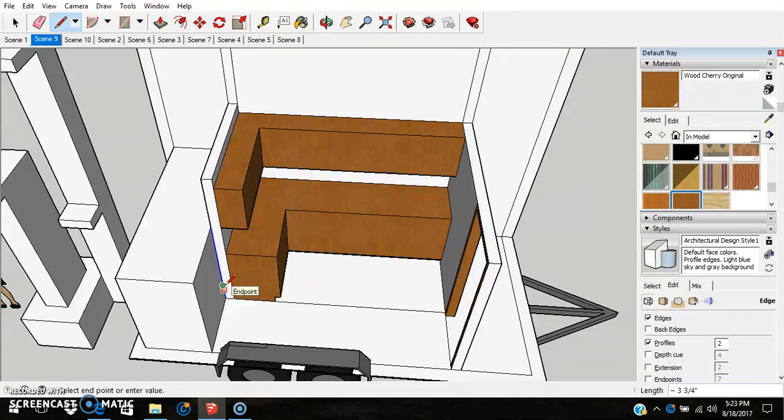It's a little high, but if we have too many stairs, we're going to be going out into the kitchen floor. What we'll do as well, measure this. This is 32. Yes, it is. So we'll start in the opposite corner with a rectangle and measure over to the marks on that line so that we get our steps.